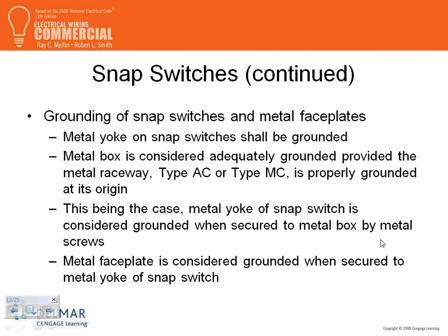On the snap switches, the yoke must be grounded. In 2005, I believe, the yoke, everybody knows the yoke. I don't have a switch, but here's the yoke. The yoke must be grounded, right? They added this one, if I remember, probably in 2006.